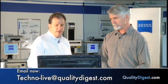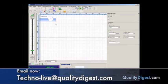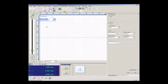Another valuable tool inside the same tool allows us to locate the stylus within its range. We're going to move the column up and down so that we stay low in the range. Because this valley is very deep in the overall shape of this part, we want the stylus to be very low in its range. So you want the valley to represent the lowest part so that everything is up from there. Right. So when we get to the highest point of the part, we'll still be inside the range of the probe. We do that simply by setting a percentage of the range that we want to use, and in this case, we've set it for 90%.